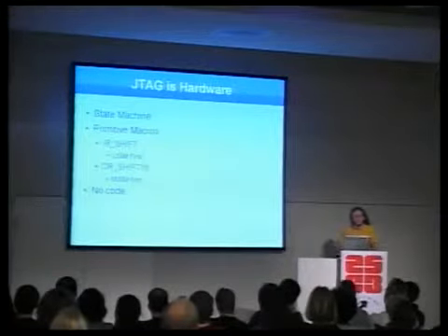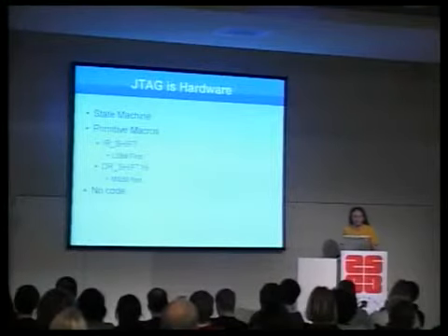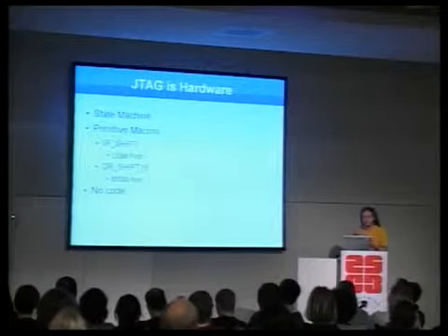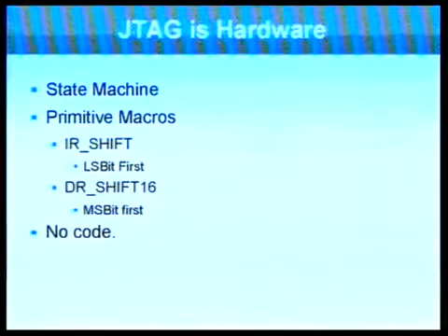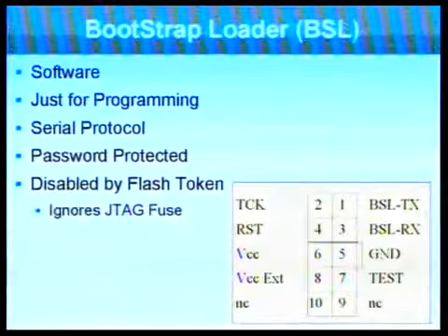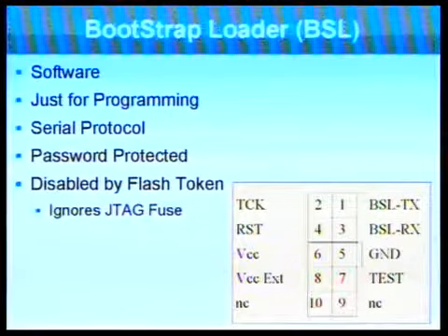But this is all implemented in hardware. You have an actual state machine. You shift into registers and you shift out of registers. And there's no software implementing this within the chip. An alternative is to use a bootstrap loader.